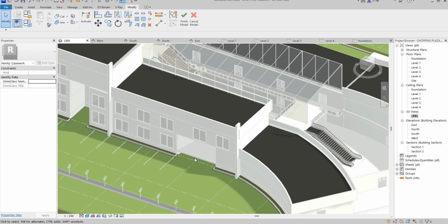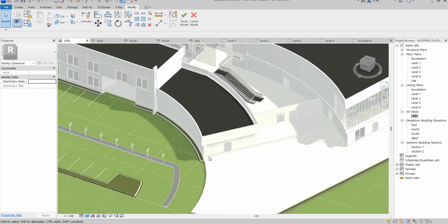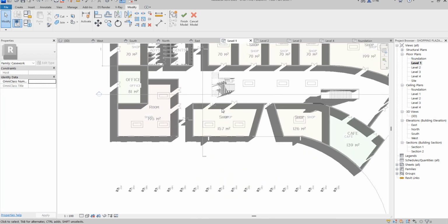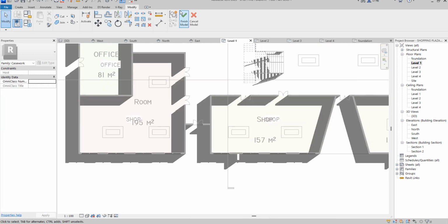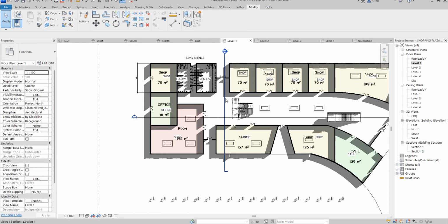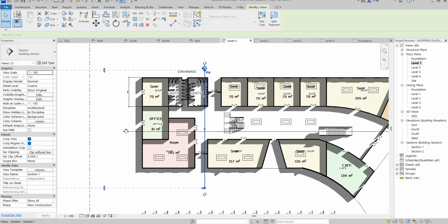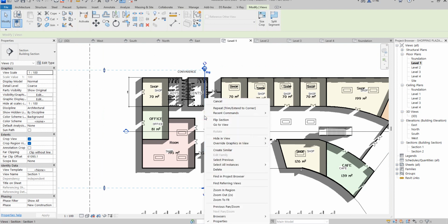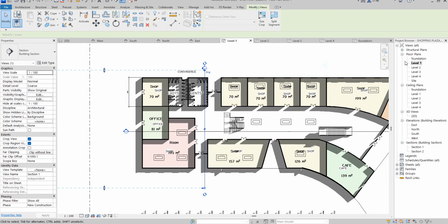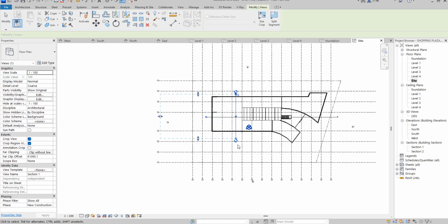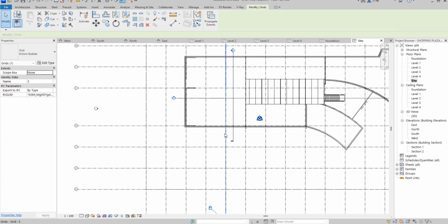So the next thing we need to do is to have a step around where we need the step to be. We need to create one step, then we duplicate it for the remaining ones. So how do we do that? Let's go on. So click finish. What I do here is that I'll bring this to this position. Let me get it down here. I will go to foundation where I can see the grid. If I don't see the grid, I can go to site to reflect that grid for me. This particular grid, grid 5, is what I want to use.